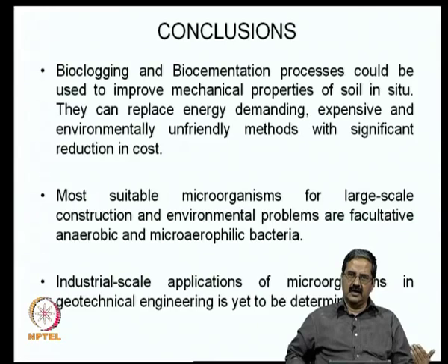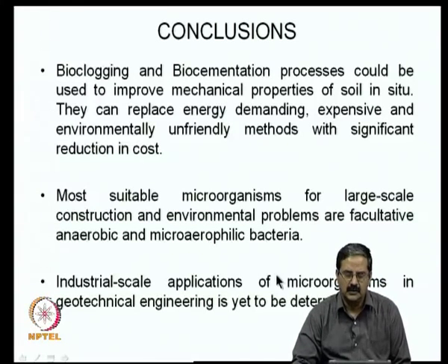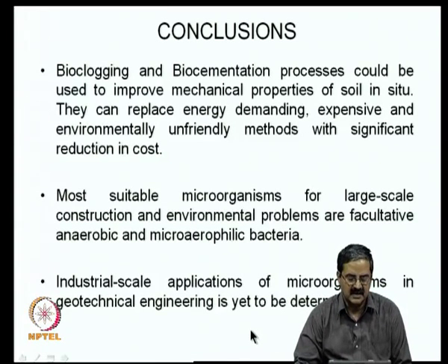Say for example, if you are reducing the permeability, you try to come out with laboratory values of reduction in permeability as compared to the original value, or if you are looking at strength improvement, look at what exactly is the order of strength required, and also do a number of laboratory tests and try to replicate the same in the field trials as well before one can go for field application. So, they have large scale industrial applications. People need to see.